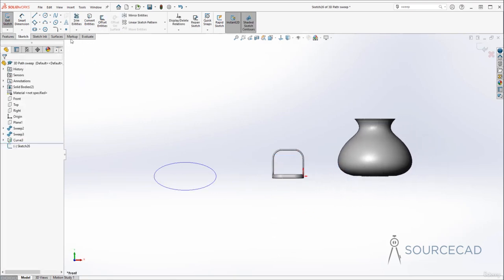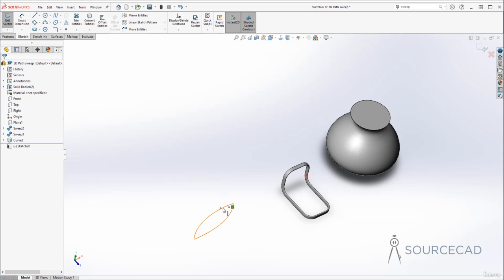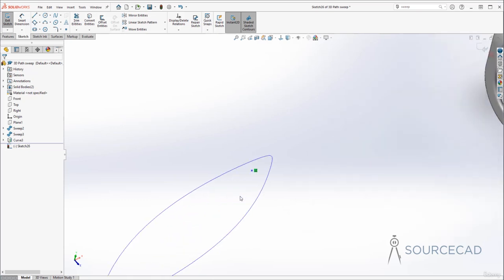All right, and on this plane, I'm just going to create a point. Now I'll just make sure that this is coincident, but as you can see, it isn't. If you change this angle, you will see that it's actually not coincident. It is coincident from that plane, and if you look at this point from that perspective, it certainly is coincident in this direction, but it's not actually on this curve.